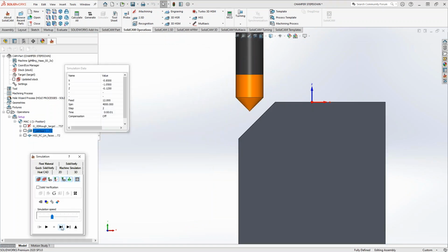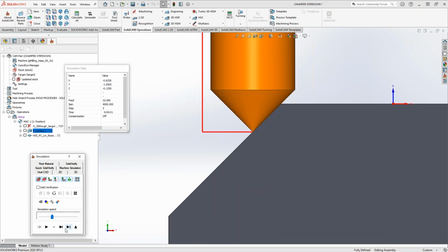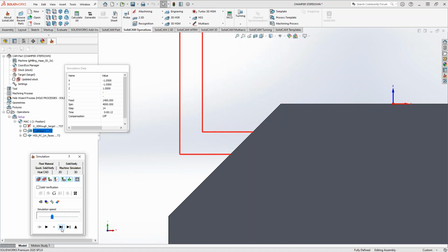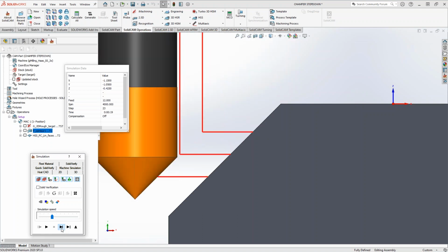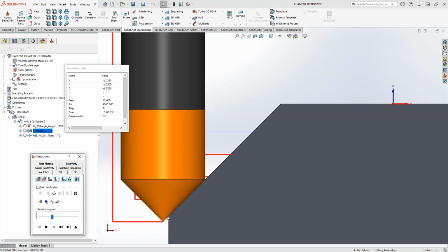So stepping through the code, you can see the tool comes down, it goes in, and it's flush. So with that offset and with that draft angle, I'm getting it to be completely flush with that face. Go right down to the bottom. There's my 50 thou right there.